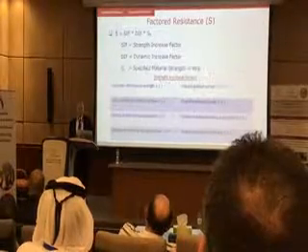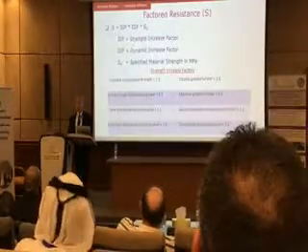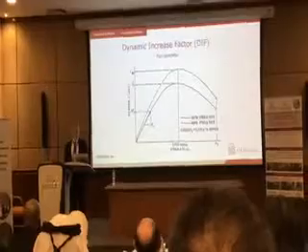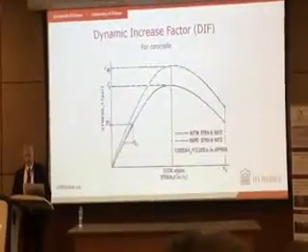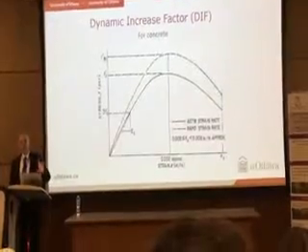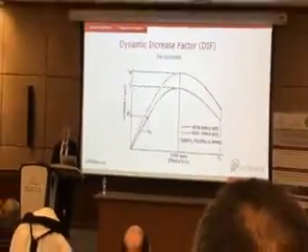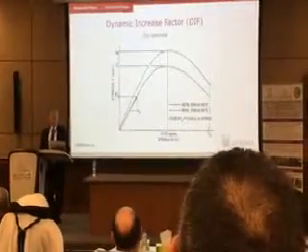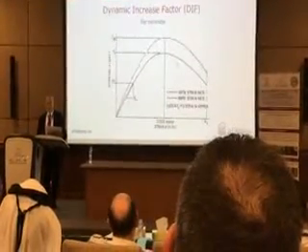So this is why you're allowed to increase concrete strength and steel yield strength by 10%. But more importantly, you have to consider dynamic increase factor. And dynamic increase factor is the strain rate effect. Okay? So if you put your cylinder, or I don't know if you do Q testing here, but your concrete sample into a machine to establish its strength, then you get the solid line, which is under static loading, right? It takes maybe 15, 20 minutes to finish the test.